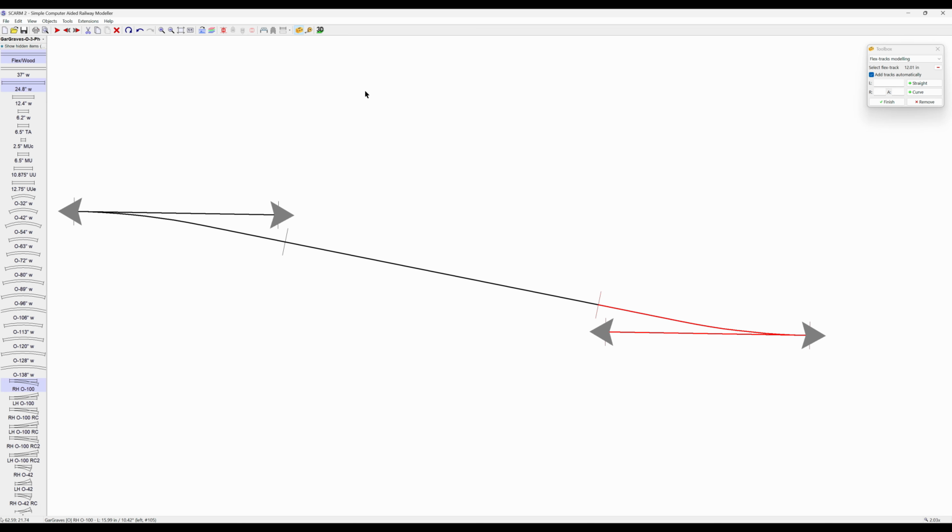Now we're going to change elevation here, and we're going to bring it to 0.3. Right off the bat, the first thing that happened is this broke. It's not connected. It's flat. This is up at 0.3. So let's bring it in, and let's get the slope going on here. And you can see we're not quite going to get that. 3.1. And I'm going to lock it in place, and now we have it connected.